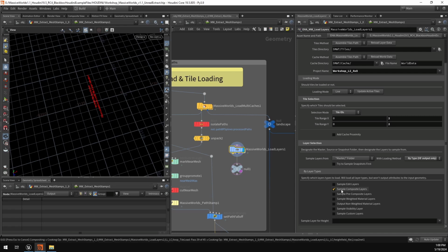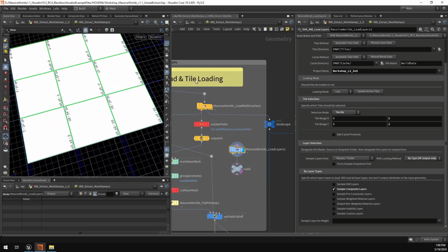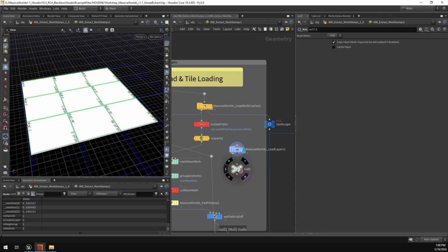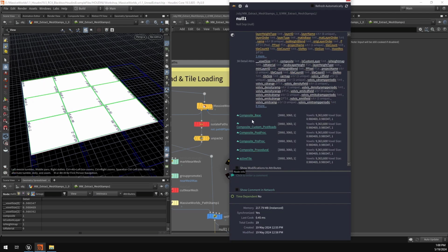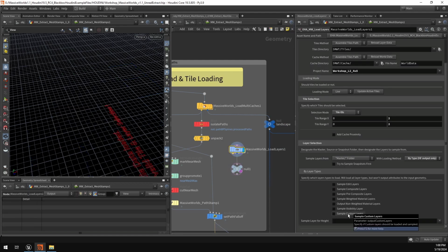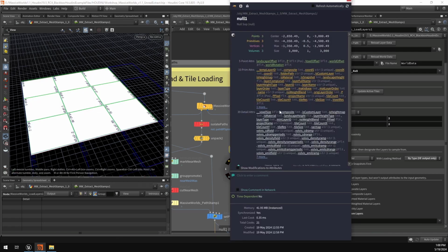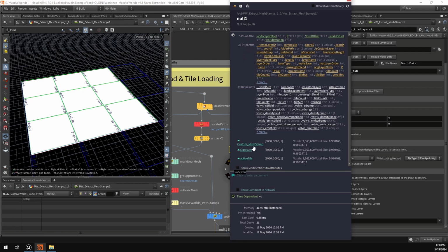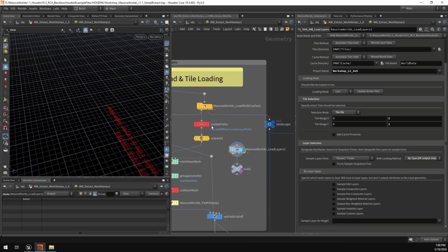This will mean that it's going to output every single composite layer, but it is going to output it as a fog type height field. This can be useful in some contexts where you need to grab all the information of a particular layer set. Alternatively, we could also try to load all our custom layers, if we have any. In this case, it is loading the exposure layer, as well as the mesh stamps layer, which is another custom layer. Anyway, that's the load layers node.